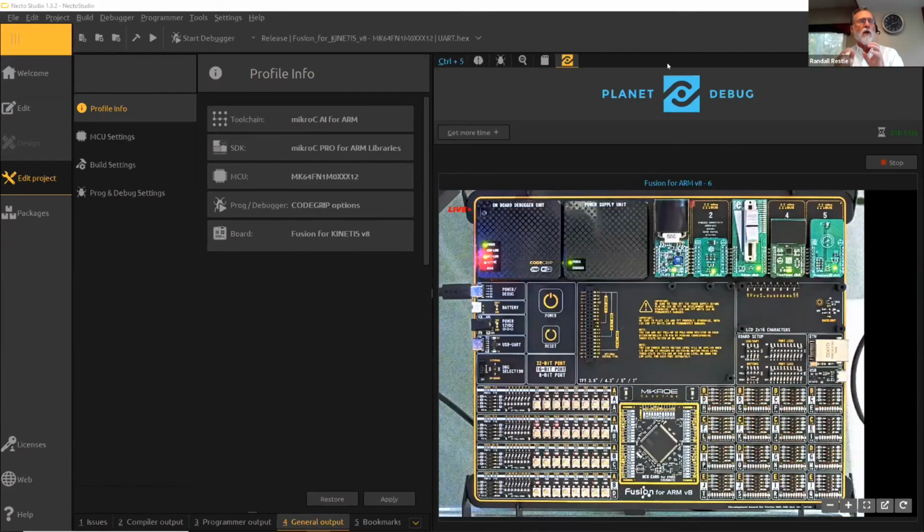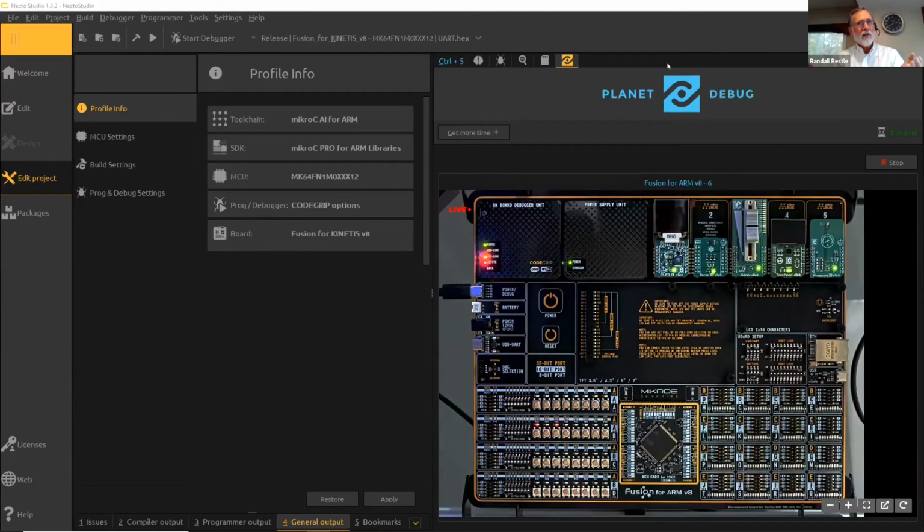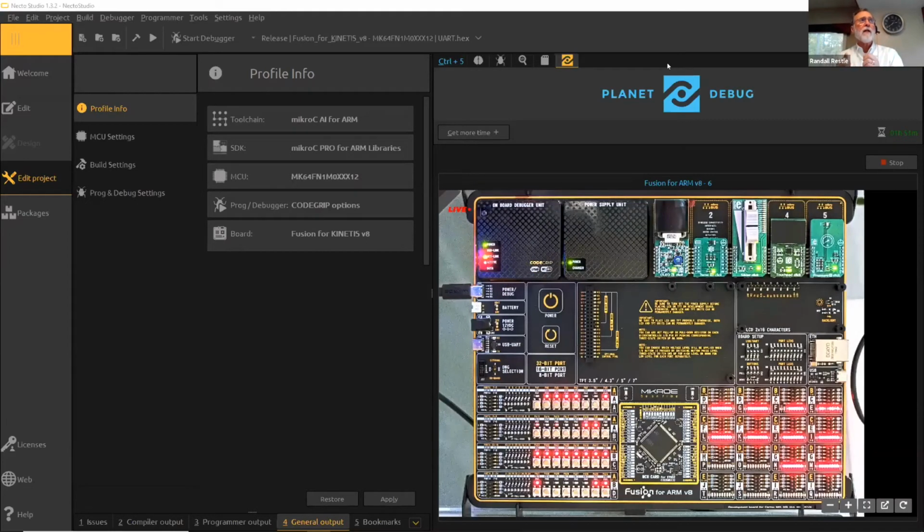But in the case of clickboards, it's more granular, and it's also very robust mechanically, so that you can have a motherboard holding these clickboards, and it's a very robust platform. But they are different platforms. You can get an adapter that goes from Arduino to Click, but I'm unaware of any boards that are exactly Arduino copies in the clickboard form factor. Again, the clickboard has this mikroBUS, which utilizes a PWM, an analog in, an I2C, a SPI bus. So it's got some prescribed interfaces to these chips that it uses. It isn't the full Arduino interface.